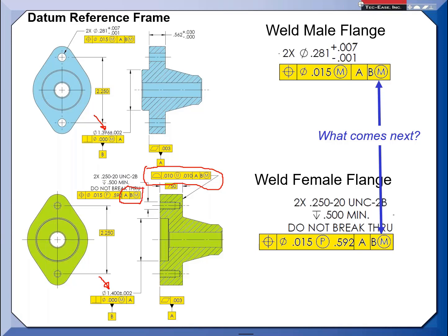Look at this here. The datums on the tapped holes are A primary, B and MMB. Then the profile is A primary, B and MMB. These two are tied together because we have a default rule in the standard saying when you have datum features with the same datum precedence, then this rule is automatically kicked in for position and profile: the inspectors would have to qualify these two tapped holes and locate this back surface in the same setup. That's invoking what we call simultaneous requirement.